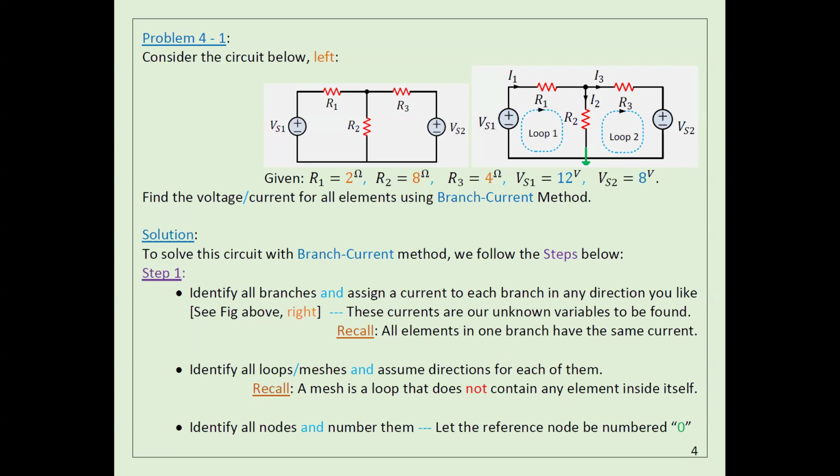Okay. So again, that's exactly what I did in chapter 3. I will try to use Kirchhoff. Because I have 3 unknowns here, I need at least 3 equations, in the 3 unknowns I1, I2, I3. Solve these equations, get I1, I2, I3. Once I get I1, I2, I3, I'm done. You can easily calculate the voltage using Ohm's law.